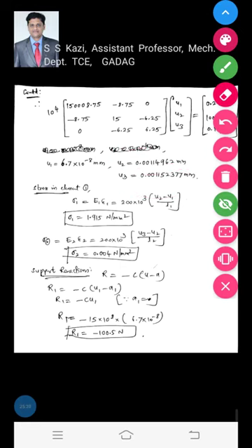This is how, using the penalty approach, we are not eliminating any of the equations. We should solve all the equations, but we should modify the terms of the stiffness matrix and force vector by adding the value of C to the support stiffness values.